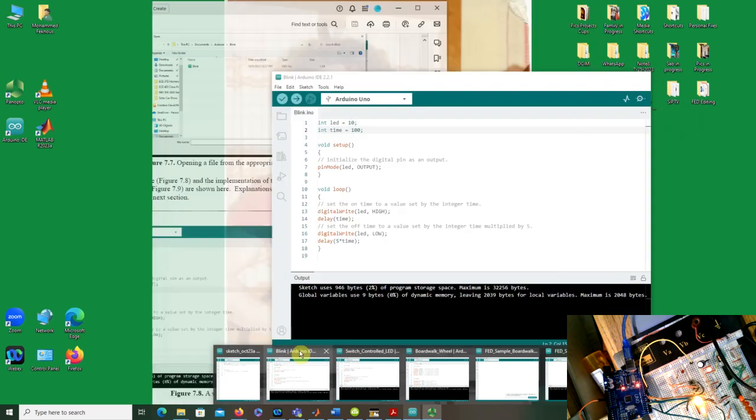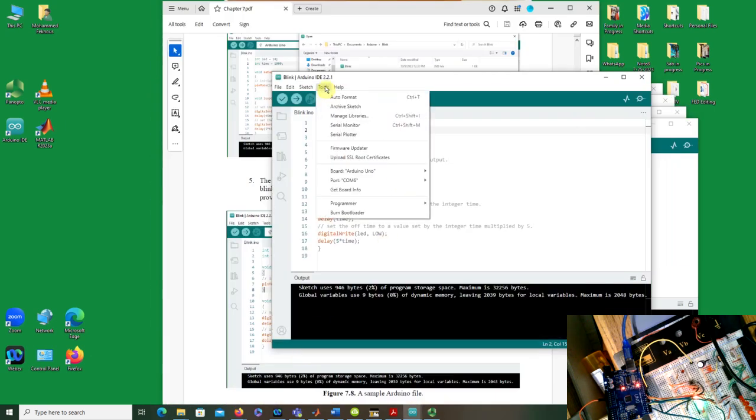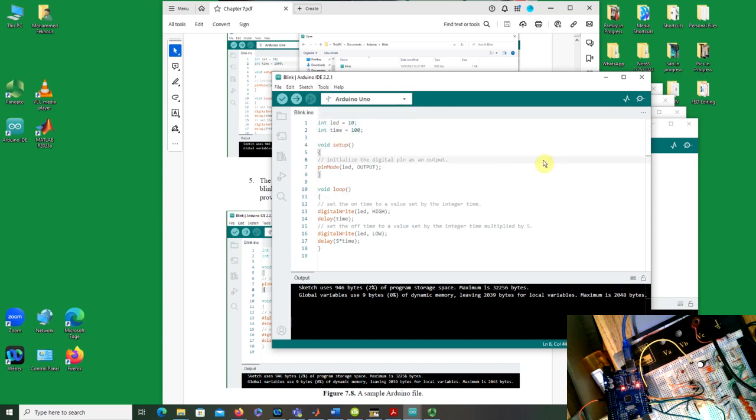So in this case, I go to the program itself, and as you see here under Tools, I have Arduino Uno already chosen. I knew that COM6, as you see here, was not exactly a very visible choice for the COM port. Most of the time, the name of Arduino will appear next to the COM port to which it's connected, but not in this case. So I assume that has been done.